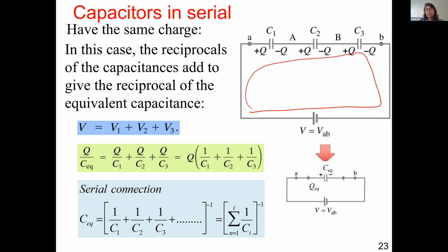When you have a series connection, since it is a single wire, they all carry the same current, but they have different voltages. Now the combination of all these capacitances we can write as C equivalent, but in this case, C equivalent is found by adding all the capacitors as 1 over values. 1 over C equivalent equals 1 over C1 plus 1 over C2 plus 1 over C3.